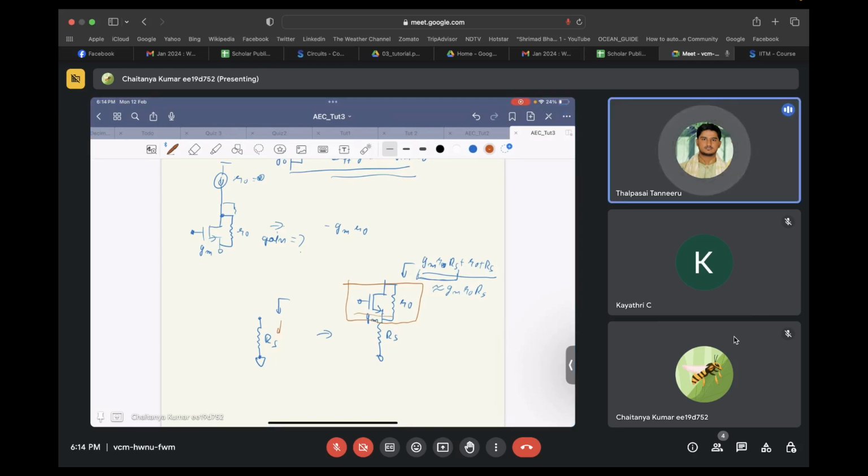While connecting the degenerative source resistance, if the MOSFET is in saturation mode, considering channel length modulation, it won't be flat; a slight deviation will be there and it moves upwards. Because of the degenerative resistance, that slope will get decreased and it will become mostly flat in the non-ideal case.